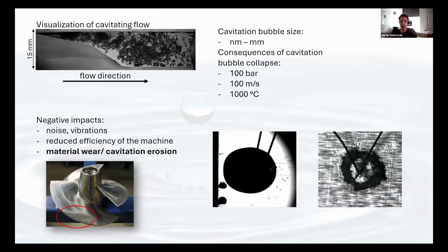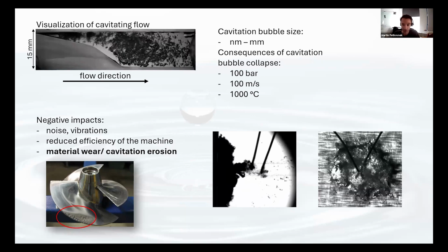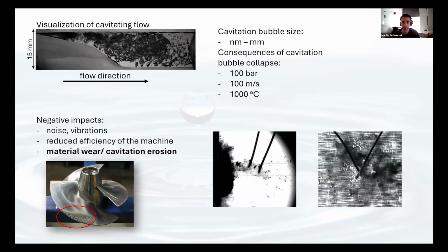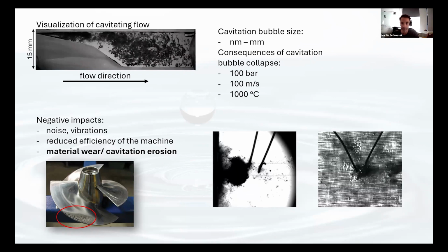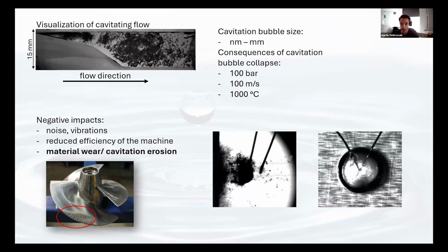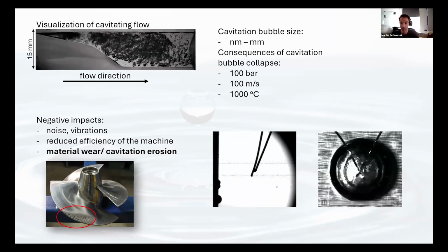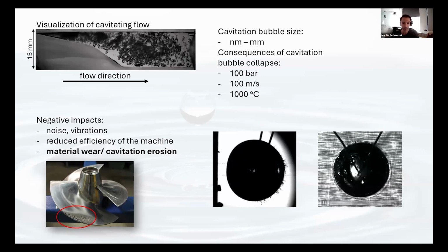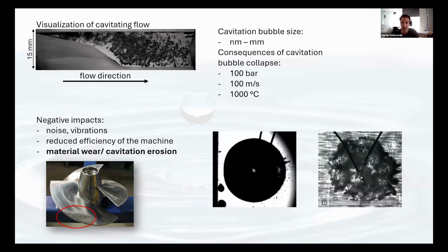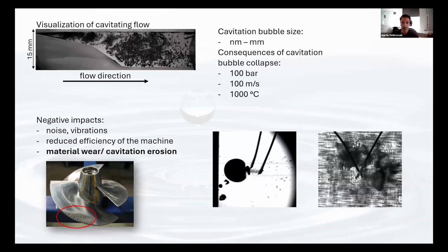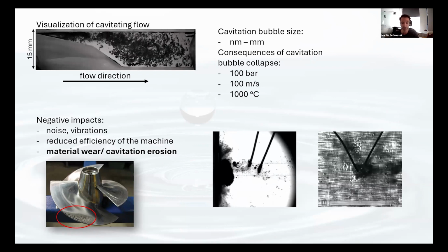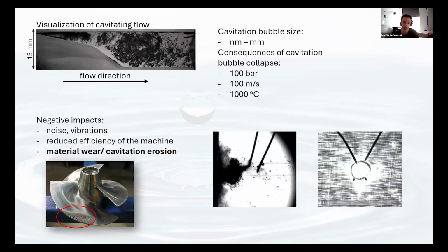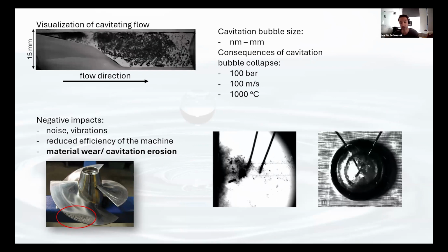Here we have a cavitation bubble formed due to electrical discharge in the vicinity of a solid boundary, from the side and front view. We can see that the bubble collapses asymmetrically towards the wall, creating a so-called microjet, and due to high velocity and shock waves causes damage on the surface, which can be seen in the video on the right side.